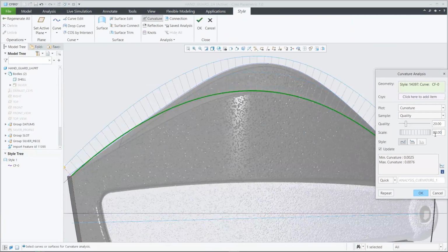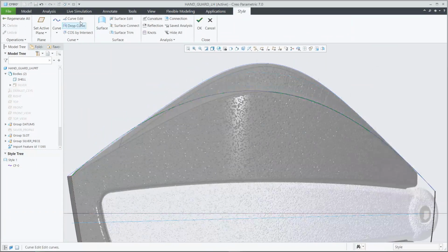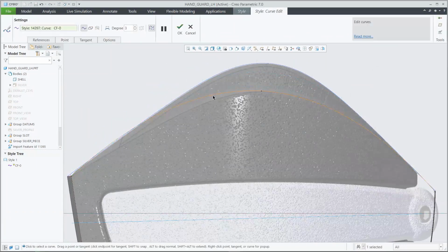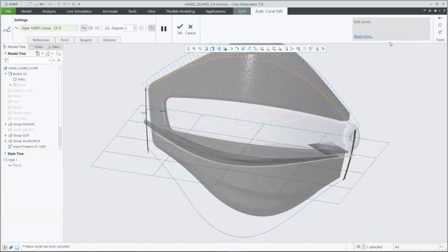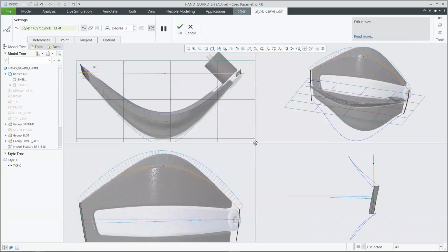And at any point, you can go through and do curvature analysis. You can see how smooth the curves that you build are, especially at any points where you might have transitions between curves. You can really start to smooth those out. And we can go ahead back into this curve here. Maybe I need to align it better with those sketches I had from before.